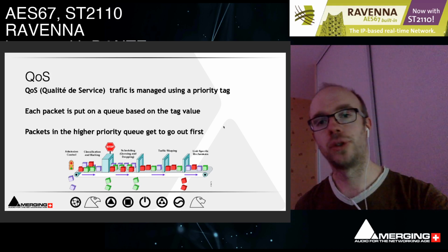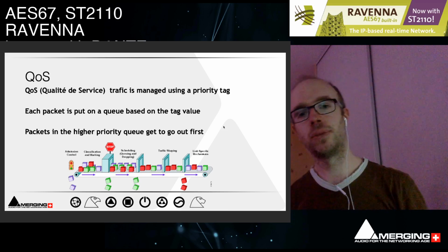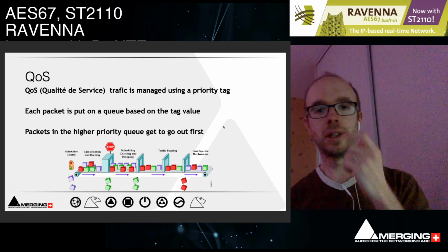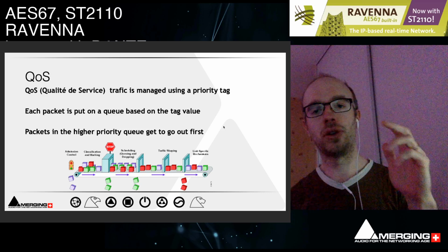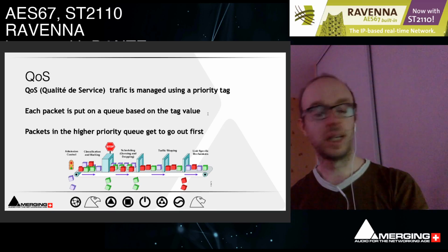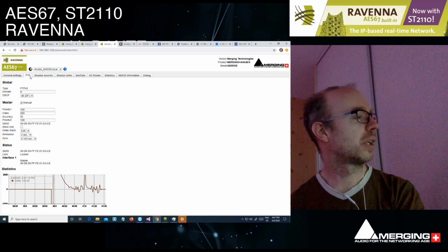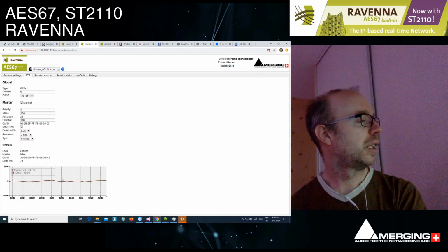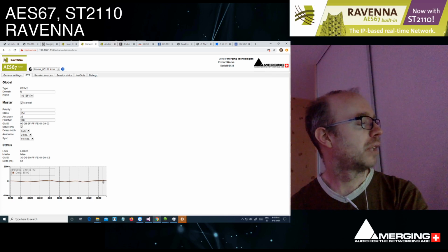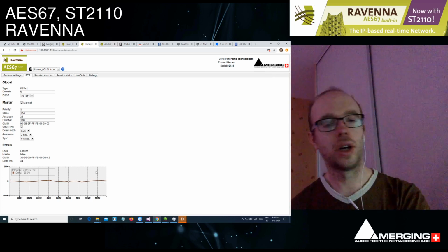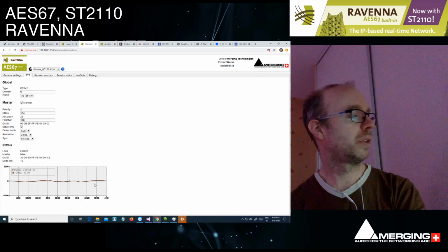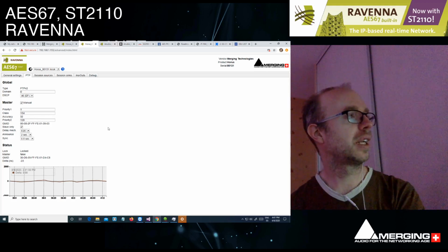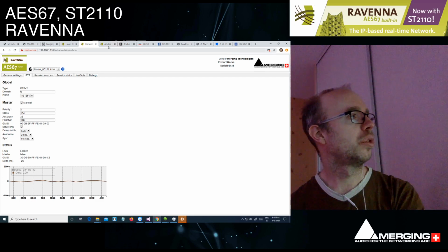You also have to use other strict things, and for PTP it's all about the algorithms on the client side that try to level and limit the noise on the measurement to get as close as possible to the device. And here we can see that it's actually working well. So this one is the master. But here we are oscillating between 85 and minus 100 nanoseconds on the network. So those precisions are really good and way inside the AES11 standards, for those of you who know and use it.